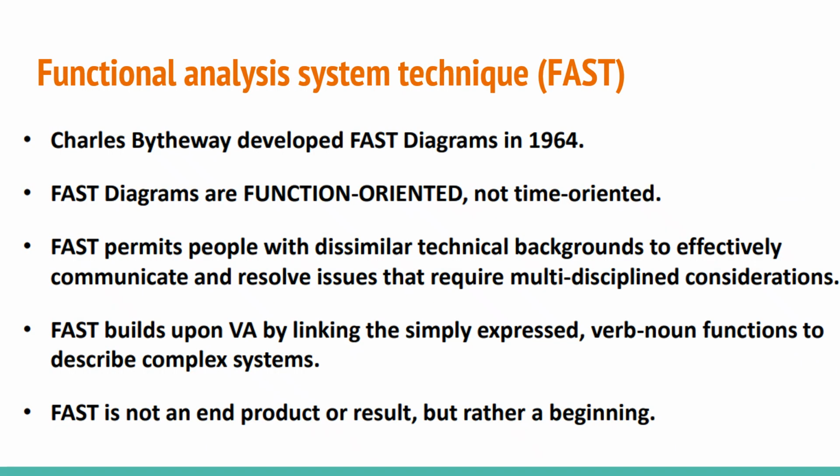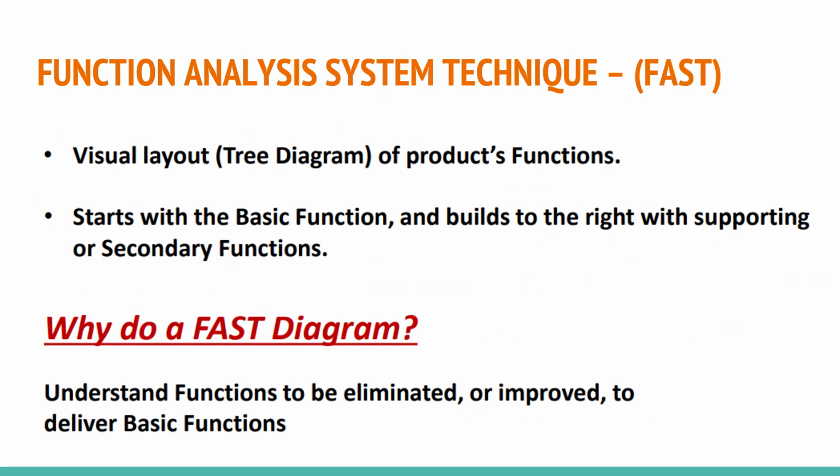Functional analysis system technique. We discuss that Charles Bytheway developed the FAST diagram in 1964. FAST diagrams are function oriented, not time oriented. FAST is not the end of the product or result, but rather a beginning. It is a visual layout, a tree diagram of the product functions. Start with the basic function and build to the right with supporting and secondary functions.